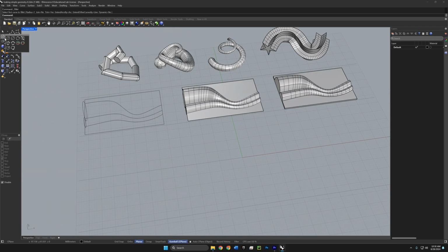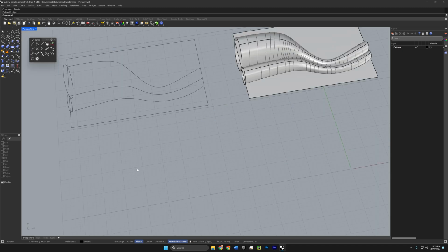Sometimes the sub-options under toolbar buttons can help speed up your workflow. I suggest spending some time familiarizing yourself with the available options. At this point, we'll look at just a couple that are nested under the polyline button. Click the triangle in the lower right of that button to open the submenu, then click the top of the menu button to dock the submenu. Then we'll create 4 circles.